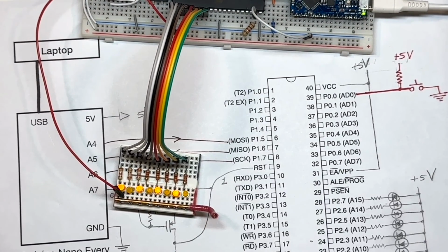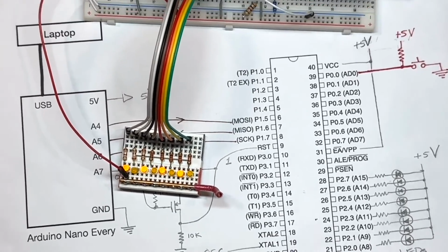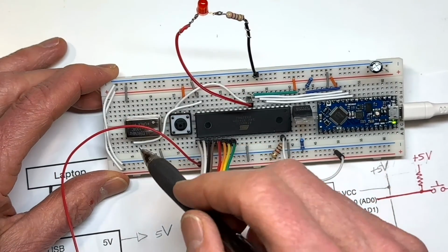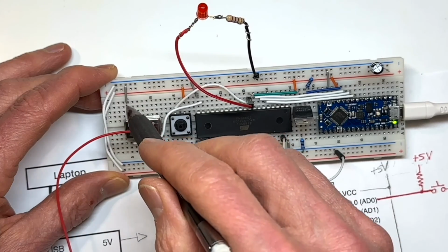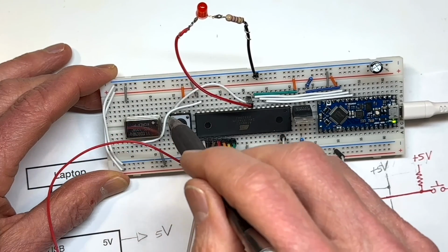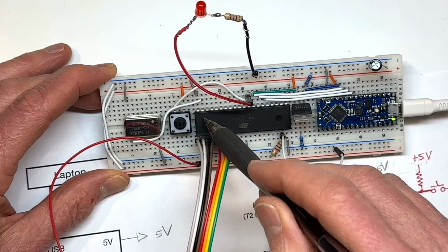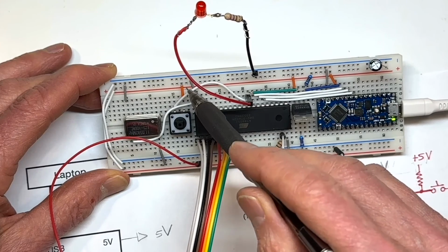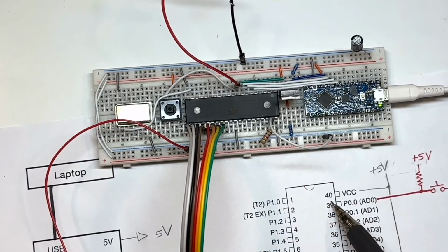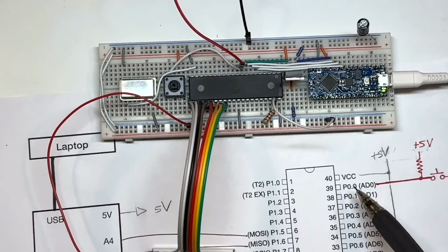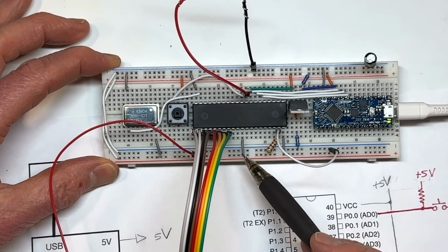Well, we've got the oscillator, which is connected to pin 19, as well as the ground on pin 20. So here's the oscillator. It is connected to power right here, and there's a connection to ground right here, and then the output of the oscillator goes to pin 19 on the 8051, and you see that pin 20 is connected to ground. You've also got pin 40 connected to power. That's this one up here, and you've got pin 31 also connected to power, and so that's happening here.